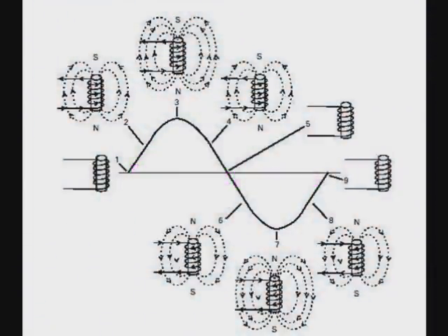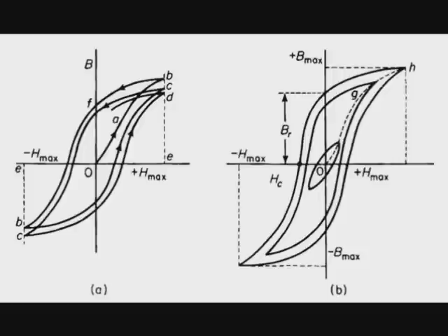In hysteresis, there are some terms I will introduce to you. First, residual flux density, Br. When H is 0, the core will retain this Br. This happens when magnetic intensity is slowly decreasing. Second, the hysteresis loop, which is the cycle of magnetization as a nonlinear BH curve. Hysteresis is flux density lagging magnetic intensity.